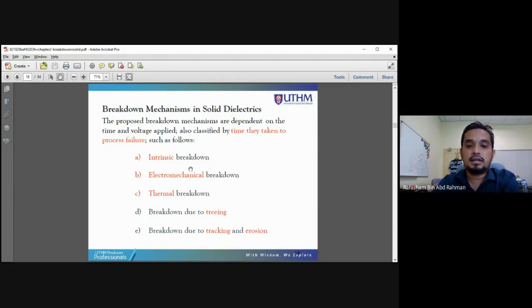Okay, intrinsic breakdown occurs in a very fast period of time, and going down the list here, the breakdowns start to take some time. Breakdown due to treeing effect: for the treeing to happen, it takes months or years.